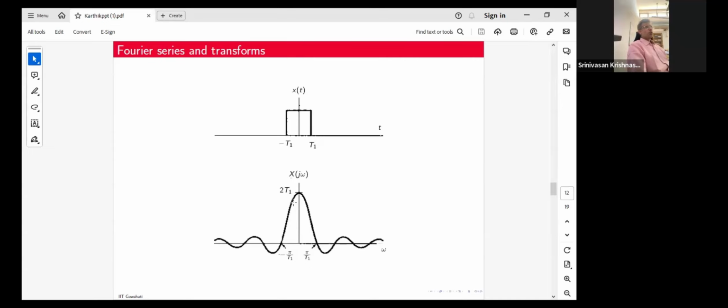Typically, how will you look at that? You will see that it is going to allow high frequency components. However, I have a speaker, which is a mechanical device. This mechanical device cannot vibrate at those high frequencies because its resonant frequency is much lower than the frequencies that my FIR filter is going to allow. So if my FIR filter allows those high frequencies, my mechanical device will attenuate them anyway, so then it doesn't matter to me. You've got to see that your FIR filter accounts for those things.